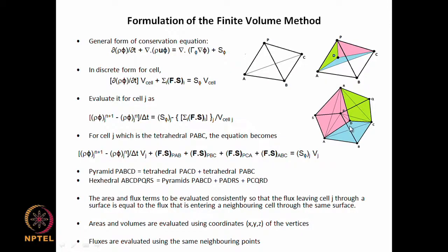What we need to do more is that we should be able to describe that general irregular shape and computational domain in terms of quadrilateral, hexahedral, pyramidal or tetrahedral elements. If we do that, over each of those elements we can then apply this formula here, and we can get an algebraic expression for the cell value in that particular cell in terms of the neighboring cell values. So, we will be able to convert this equation into something like A phi equal to B.